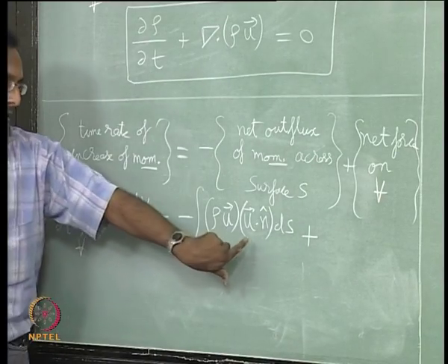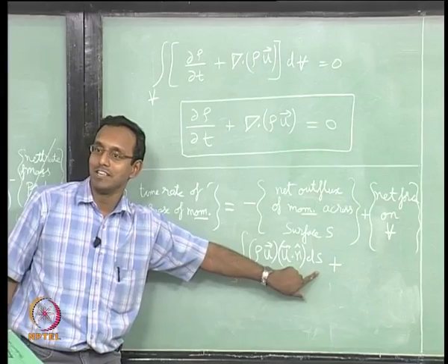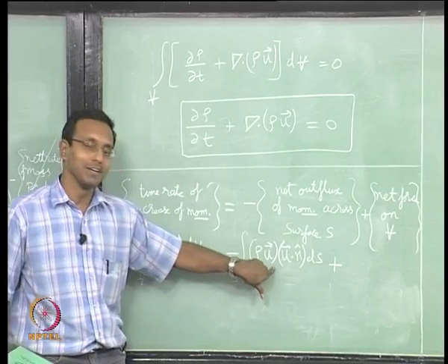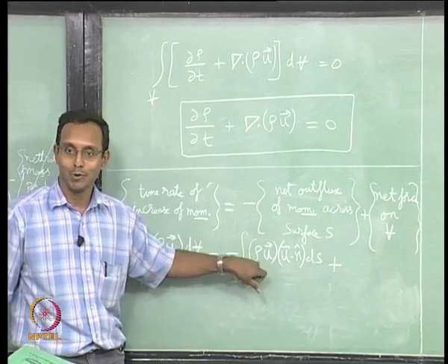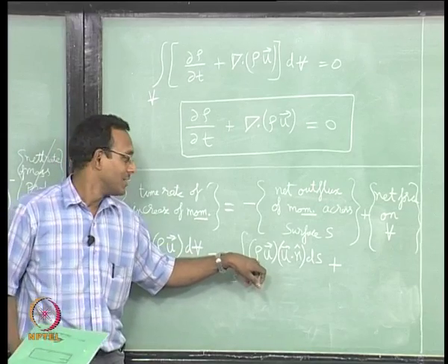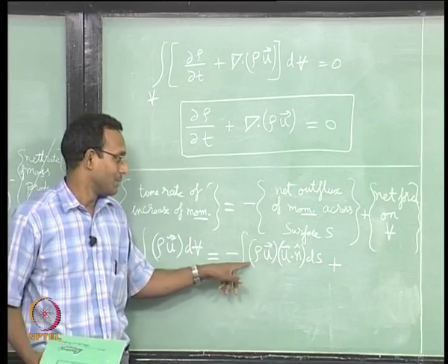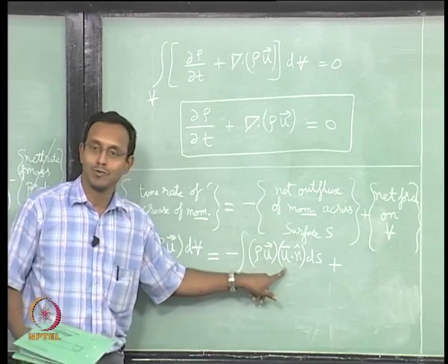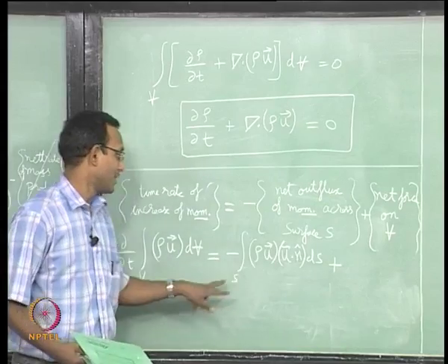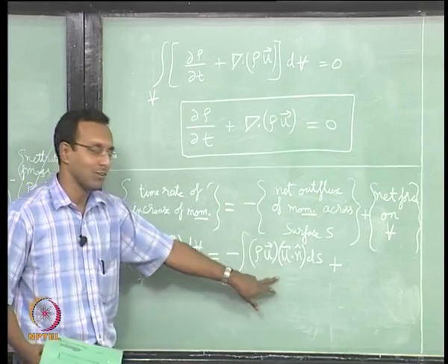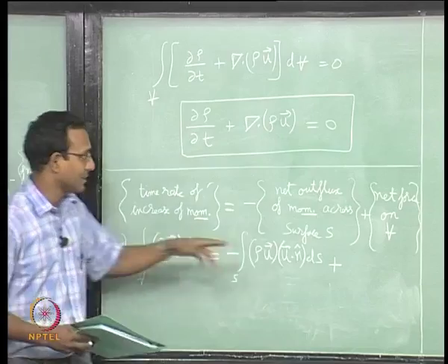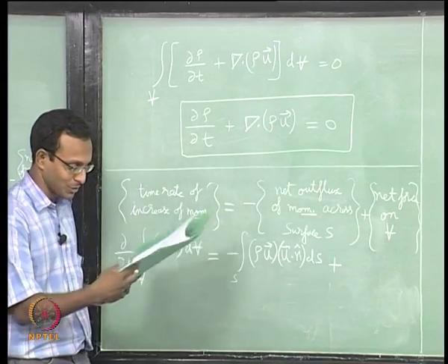This is your flux term, again we said u dot dn times ds times the quantity which is being transported. Previously it was rho because that is a mass per unit volume. Now we are thinking about momentum per unit volume that is being transported. So, it will be momentum times this flux quantity. Okay. That is your net flux, minus of the net outflux. We have this. Remaining terms we are just thinking about net force on the volume.